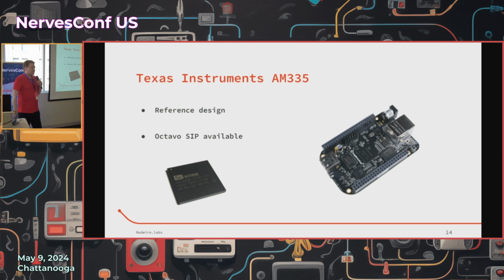This is an open hardware design, so this is published by BeagleBoard. It's on their website. And that saves a lot of time for being able to use or replicate all the hardware on there. Especially where that comes into play is how you're tying the processor to the RAM, for example. That's a high-speed electrical interface, and there's electrical design in that which can take time to get right. So to shortcut that process, you can go grab the reference design off the website that has the schematics and the PCB layout and literally copy-paste that section of circuitry. And then spend your time building the low-speed, lower risk peripherals on top of that.